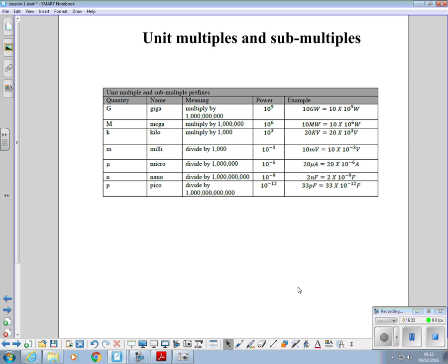What you have to be careful of when you get a mixture of those in formulae is that Ohm's law will only work if all the quantities are in the same base. So amps, volts, and resistance. One way to deal with that is to use the multiples of 10 to deal with the fact that you've got volts and you've got milliamps.